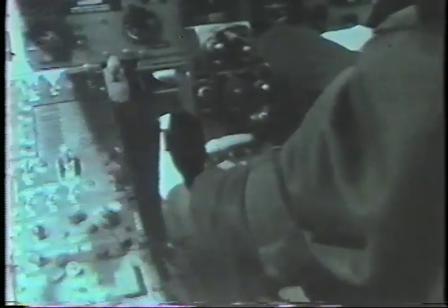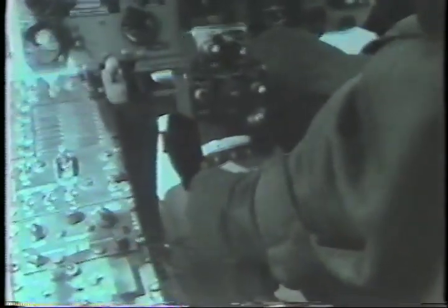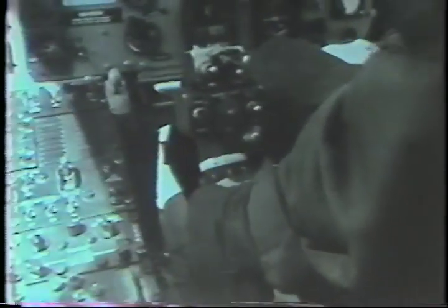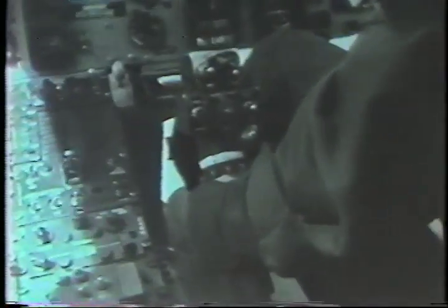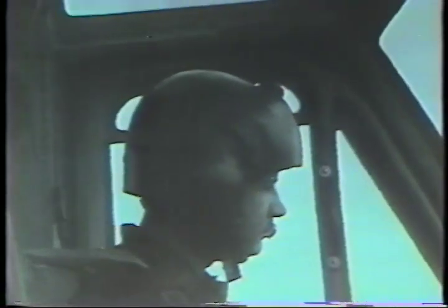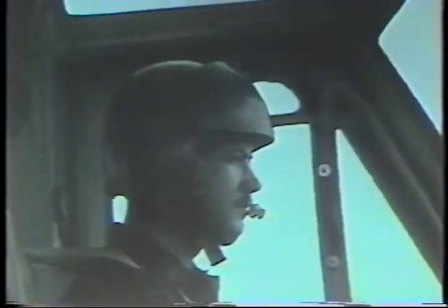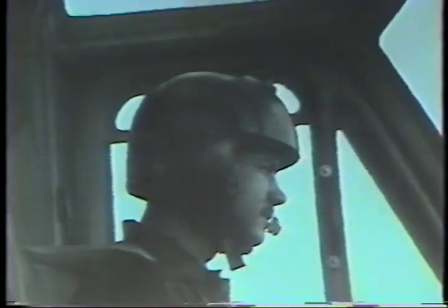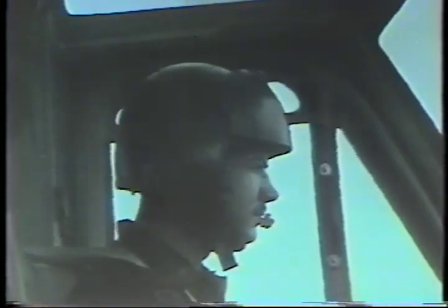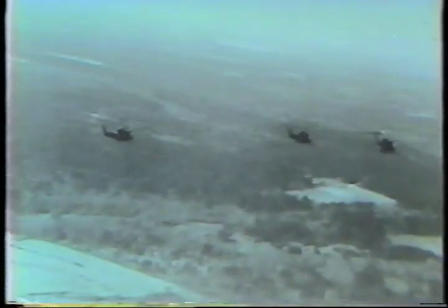During a turn, the inside wingman will have to decelerate slightly, while the outside wingman accelerates slightly to maintain relative position in the formation. When anticipating the degree of bank, caution must be observed to eliminate fixation. Should it become necessary to exceed a standard rate of turn, it can best be accomplished by slowly continuing to increase the degree of bank until the desired turn is established.